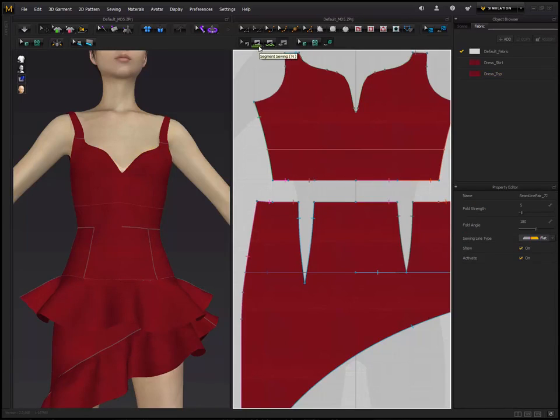So the next option is the sewing option. This option is the basic sewing. So you can sew anything into any other point. Right now, the sewing option only works with the original points you added, the little vertex dots. Right here you have 3 dots. It'll only stitch in this area into this area. It can't split in the middle. It could only go from one point to another point.